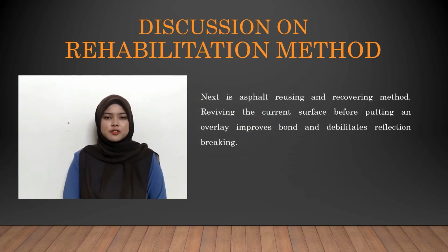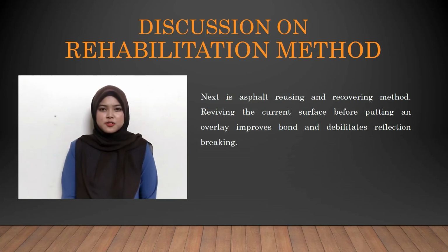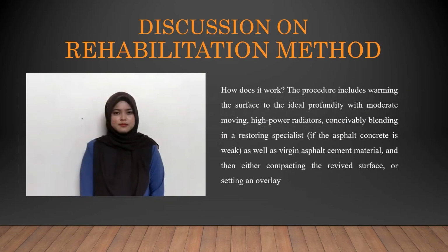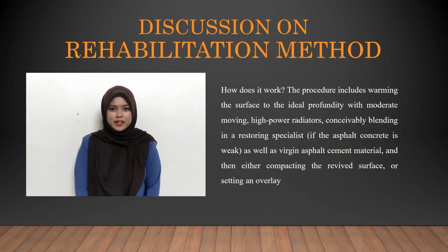Next is the asphalt recycling and recovering method. Reviving the current surface before putting an overlay improves the bones and debilitates reflection cracking. How does it work? The procedures include warming the surface to the ideal depth with moderate moving, high power heaters, potentially blending and restoring agents.